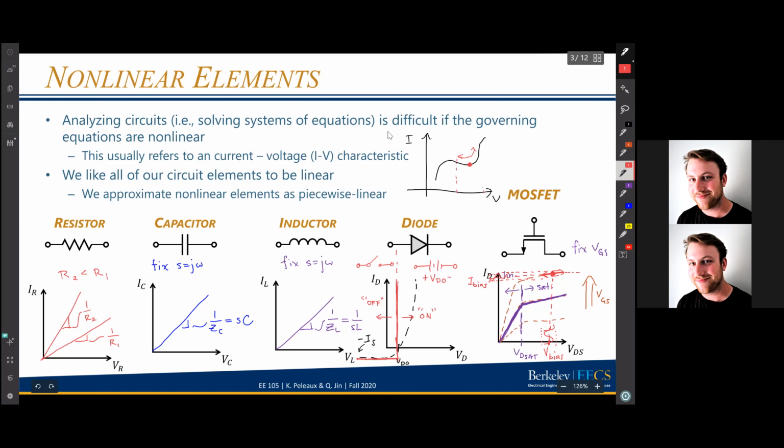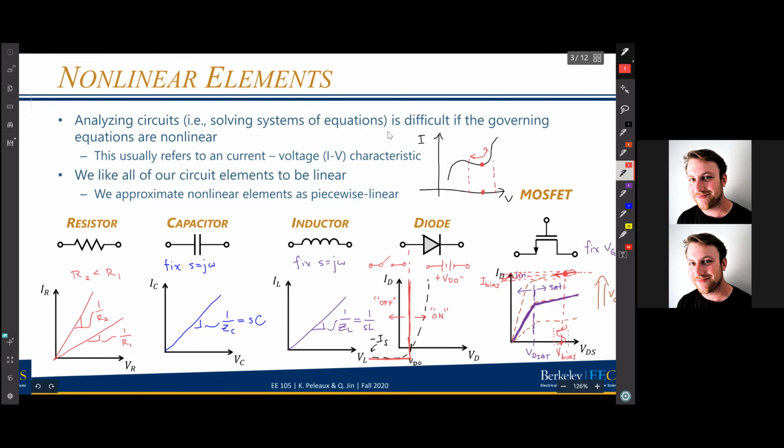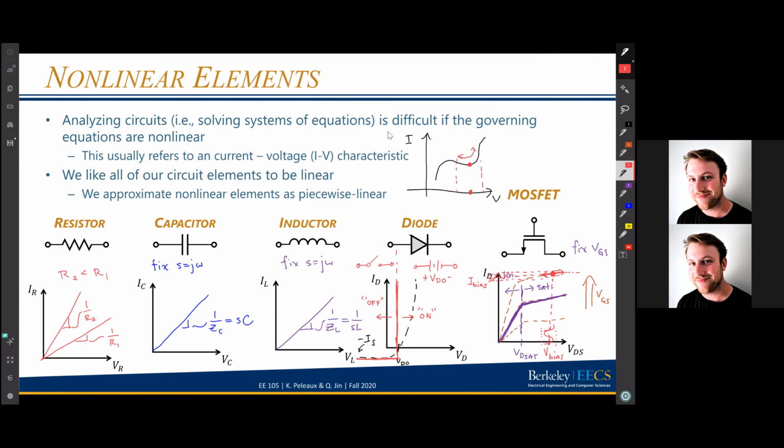curve, so if I take that bias point and I wiggle it too much, then I will really be traversing the full curve, or I should say I'll be traversing that curvature such that my IV characteristic will just be very nonlinear, right? So this is like a large signal excitation. If I want this to be linear, what I have to do is keep my amplitude very small.